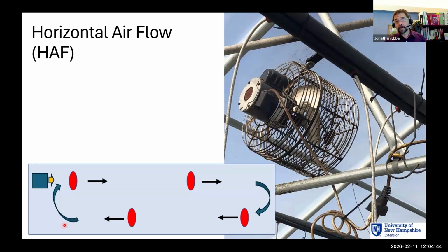When we talk about airflow, when we're talking about ventilation, we're talking about getting air out of the house. And so sometimes our horizontal airflow can start to compete with our ventilation airflow. So in an ideal world, we would be running this horizontal airflow when the furnace is on and we're not venting. We'd run it when the furnace is off and we're not venting, but we would not run the horizontal airflow while we are venting in an ideal world. And there are some real life exceptions to that, which we can talk about.